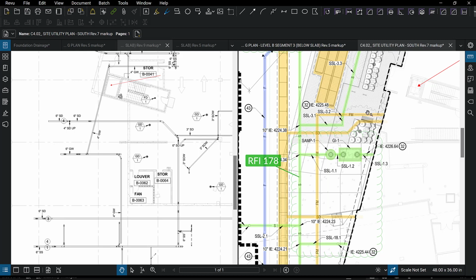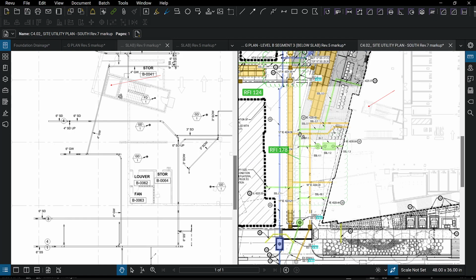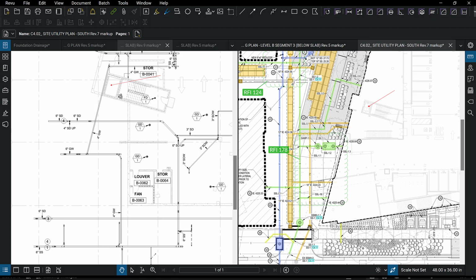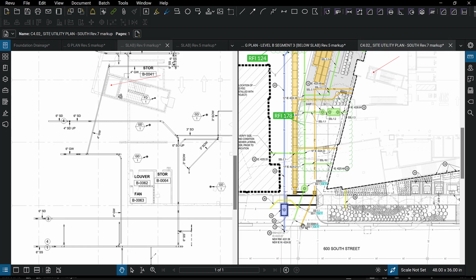At least the civil designer says we want the forced main, the one under pressure, the one that's going to be pushing water from a pump, to be separate from this storm drain one, because one of them comes right into a collection box and the other one goes into this infiltration system. So they want the one that's just going to trickle slowly to go here, and the one that's going to be pushing a lot of water to not hit this infiltration box and go hit that storm drain back out to the main city storm.